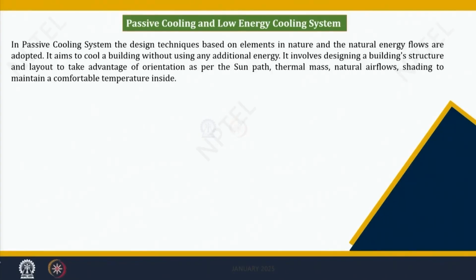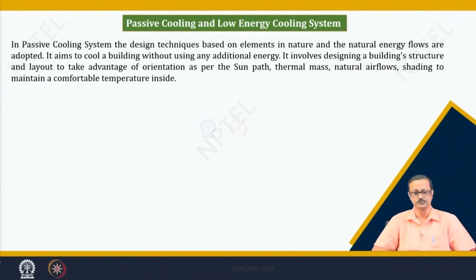As and when we talk about energy efficient design, we always refer to two simultaneous systems. One is the passive cooling system and one is the low energy cooling system. So what is a passive cooling system? Passive cooling systems are based on a design philosophy which is driven by nature and by natural energy flow that is adopted in our building design.